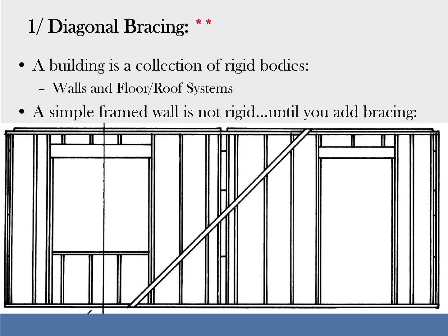Or you can put sheathing, plywood sheathing, OSB, oriented strand board side sheathing on that wall with a proper nailing pattern. Now that diagonal brace could be a temporary thing nailed on the side, or you could let it in, as they say, where you literally draw some lines, trace them along there, and run saw cuts through there, dados we call them, so that you could set it into the face and leave it there permanently as part of that wall. We'll look more at framing in the second exam when we get to the second quarter of this course.